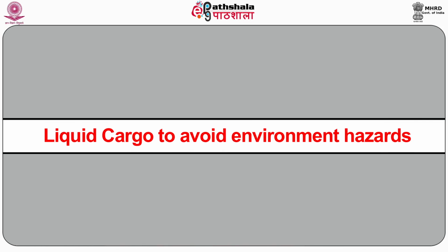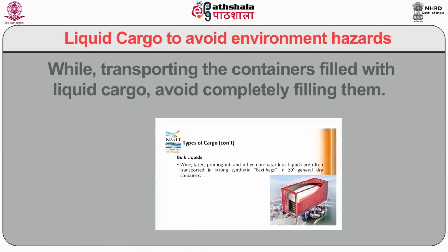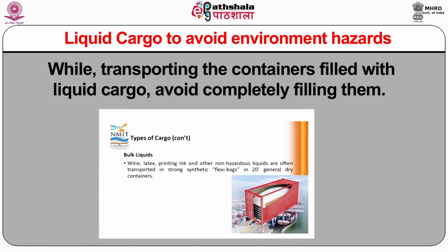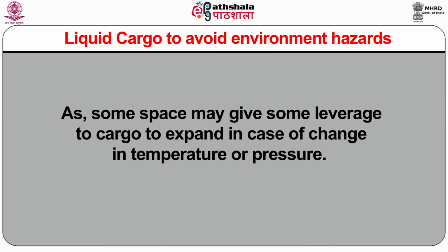Liquid cargo, to avoid environment hazards. While transporting containers filled with liquid cargo, avoid completely filling them, as some space gives room for the liquid cargo to expand in case of change in temperature or pressure. Also, all the seals, valves and caps should be firmly closed and proper marking made outside the container to keep the cargo stakeholders informed about its nature and type.